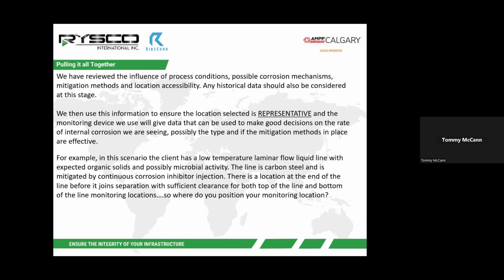So in a scenario where our client has a low temperature laminar flow liquid line, expected to see organic solids materials, potential for microbial activity, their system is carbon steel, they are mitigating that by continuous inhibitor injection. There's a location at the end of the line before joint separation, and there's sufficient clearance for both top of the line and bottom of the line monitoring.